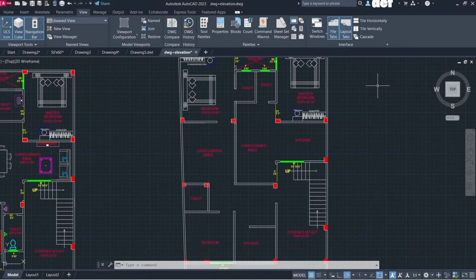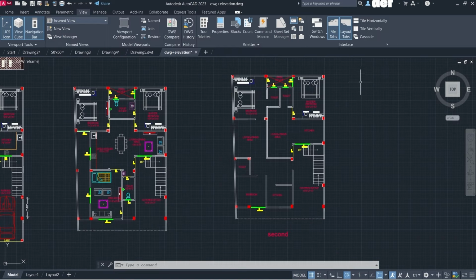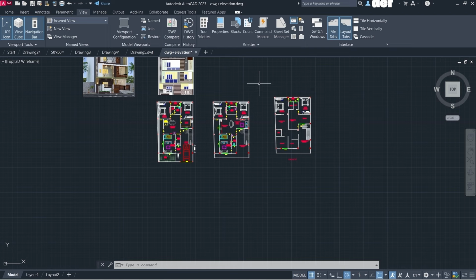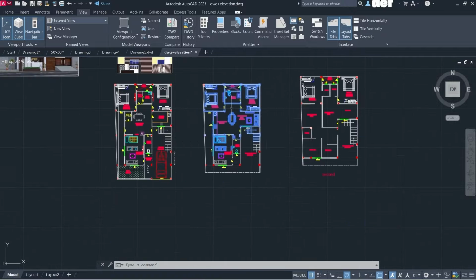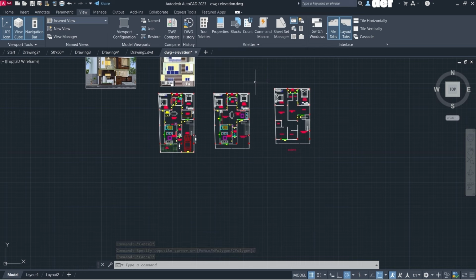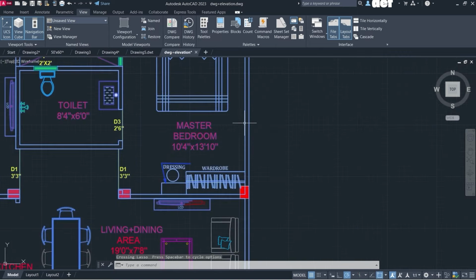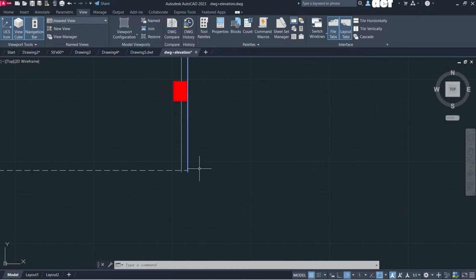And the third method which you have to know is the lasso. Press and hold the left button of the mouse and then move your mouse to the right side of the first click, then it will automatically make a lasso selection window through which we can select a specific area, and we will end it like this, and the area through which the lasso is going will be selected easily. If you want to make a lasso with this green window, simply click on the object and make a green window like this. The whole boundaries which this green window or crossing window crosses will be selected wholly, like we have selected this line from here, so it will select this whole line like this.